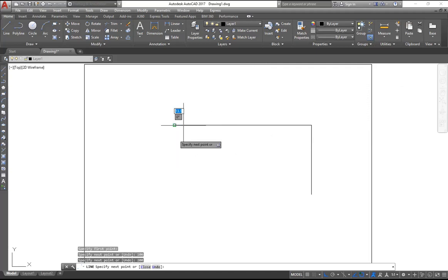Now look up here, I need to draw a line that is 150-degree inclined to the 200 line, and that line will be 100 units. So, and now you can see my orthogonal mode is obstructing my movement. So I come here to take away my orthogonal mode, I turn it off. Now my line can now move freely. From here now, you see I can type 100.